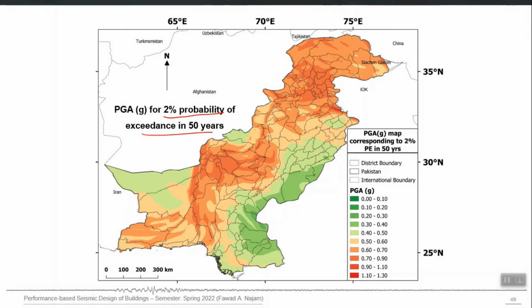So ideally, yes, it is possible that the zone of a particular area is changed as a result of new PSHA. It may go up or down depending upon the new results, which are supposed to be more accurate, right? But in this new seismic design philosophy, you don't need those zones, PGA based zones. You directly need SS and S1, right? So actually this map doesn't have direct application nowadays, this PGA map in the seismic design procedure.